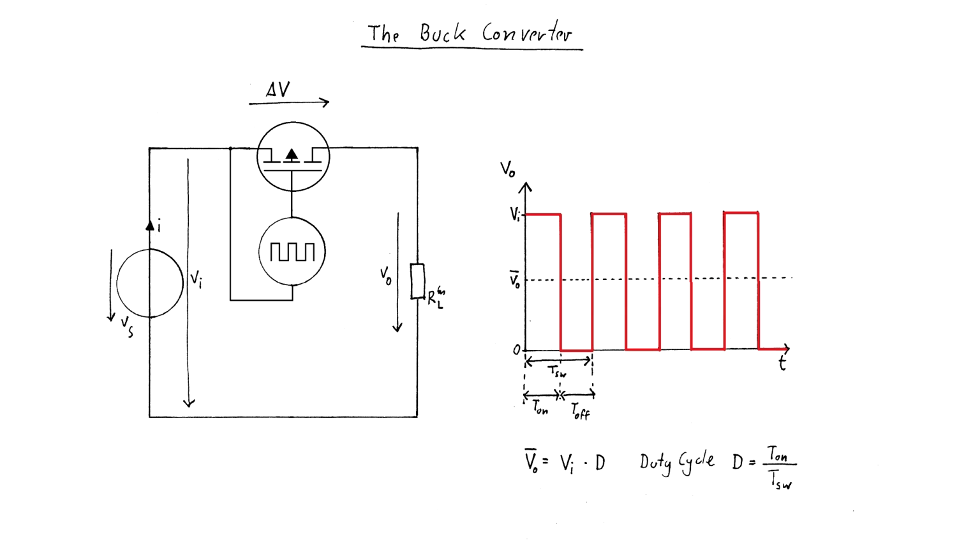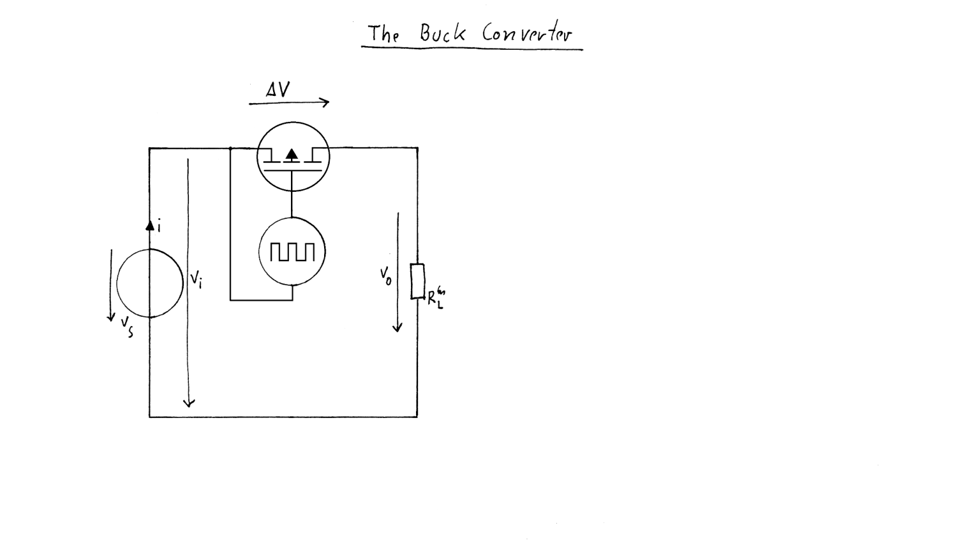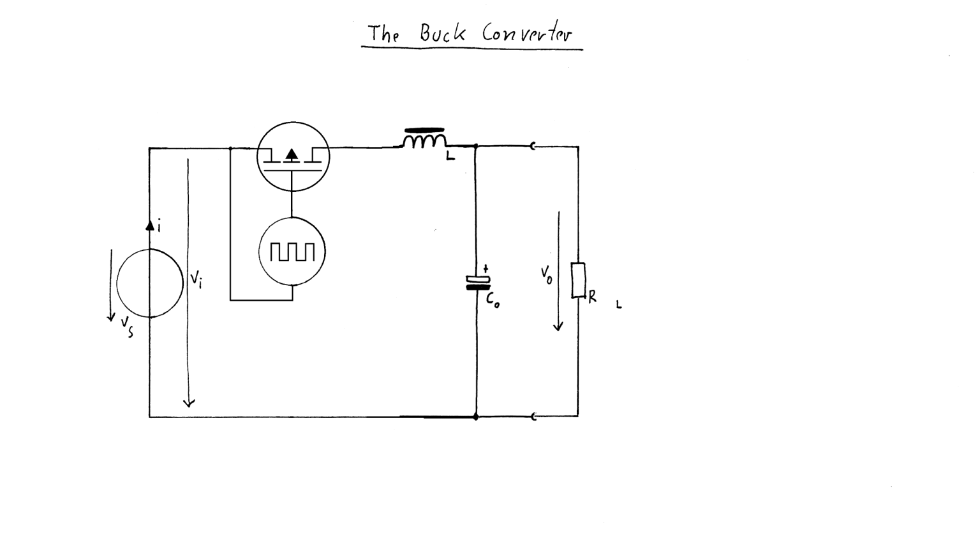But as I mentioned before, many other devices, unlike the light bulb, cannot be driven by a pulse width modulated supply voltage directly. They need a truly constant voltage, and that is why it is necessary to find a way of physically averaging the output voltage of the converter, rather than relying on the purely mathematical mean voltage we've been using as of now. That averaging process is accomplished by adding an LC filter and a second switch to the circuit.